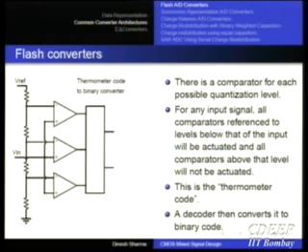The problem is that the dynamic range of accurate resistors that you should have is too high. Right? So suppose you have, let's say 8 bit, then one of these resistors is R, and the other resistor is R by 256. Now what is the absolute accuracy that you need in this R? If this R has an error of 1 in 256, then this error itself will swamp the current supplied by that much larger resistor. Right? So it is this thing which will limit now the corresponding D to A converter that you have.